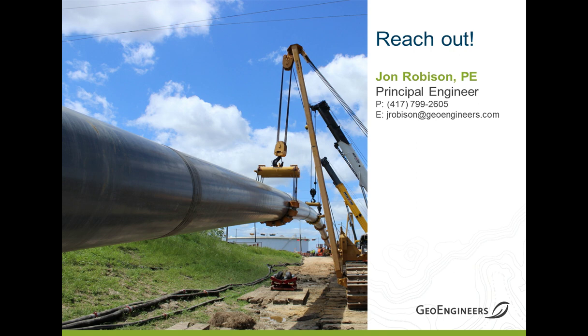Okay. And how is the space between the pipe and the overcut addressed? That's what we talked about, the lubrication fluid. That's where that sits. If your pipe was near the ground surface and you were concerned about settlement, we did have one project where we had ports in the casing pipe and we post-grouted the installation. That's the only direct pipe that I'm aware of that has done that.